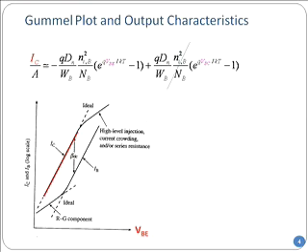You can see at high current level, the I_C current gradually flips over, or gradually rolls over. That's the ambipolar type transport, that is the high injection, those types of things. So that is something we are not showing there. So the current will gradually roll off.